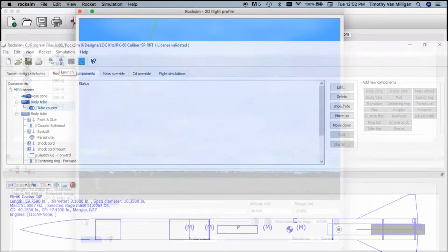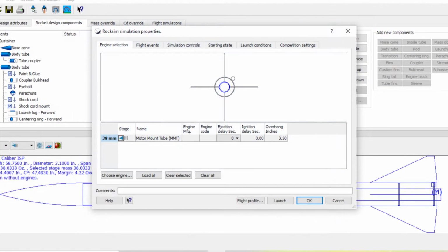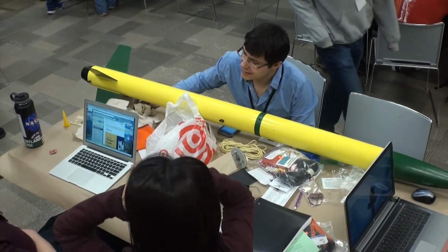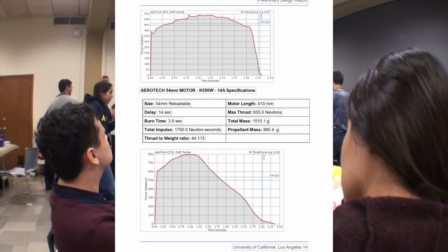Something to note: initial simulations typically have a margin of error in accurately predicting the final weight of your fully loaded rocket by plus or minus 10%. Drag considerations will also likely be slightly off. This means that your predicted altitude may also be off. So when your rocket is complete, you will need to carefully weigh and measure it. If the rocket is heavier, you should have already simulated a slightly more powerful motor as a backup.